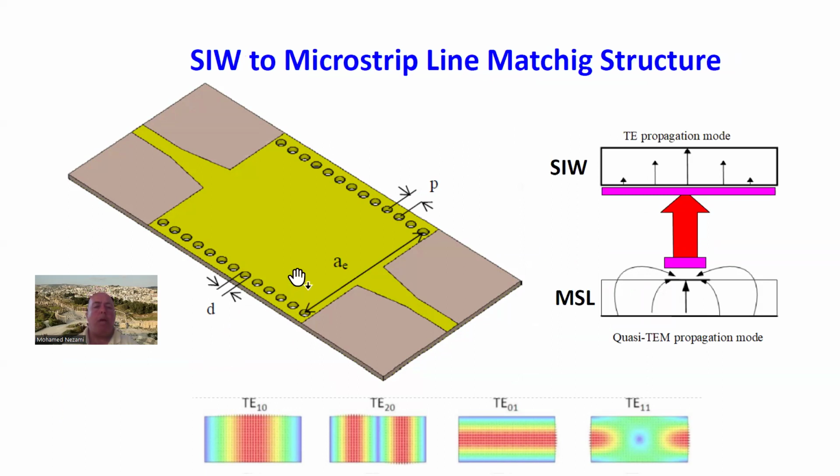So here's the substrate integrated waveguide, with vias of a certain diameter and a certain width of the waveguide, which is the distance between the vias, the electrical walls in here. And then we have the pitch of the via holes, and that's the P in here. This is really an electrical wall, so you can think of this as if you would put a ground wall on the ground side that connects the bottom to the top.